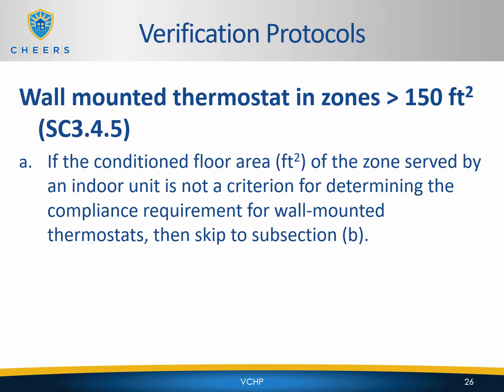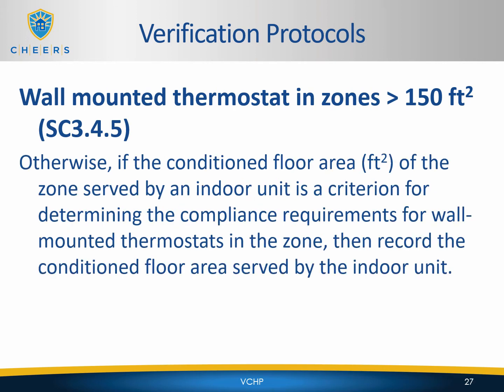If the conditioned floor area of the zone served by an indoor unit is not a criteria for determining the compliance requirement for wall-mounted thermostats, then skip to subsection B. Otherwise, if the conditioned floor area of the zone served by an indoor unit is a criteria for determining the compliance requirements for wall-mounted thermostats in the zone, then record the conditioned floor area served by the indoor unit.